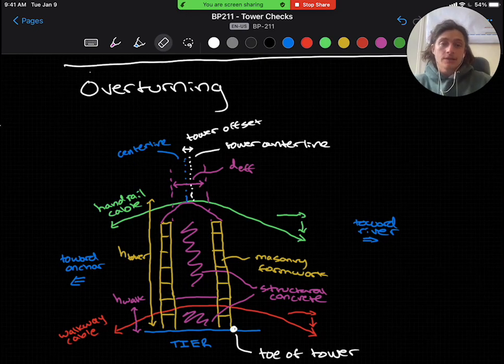So we have two center lines here. We have a bridge center line that is going to be consistent between the two tower columns where the cable sits, and we have the tower center line, which is going to refer to the tower center of mass, where that value of P tower, the weight of the tower, acts through.